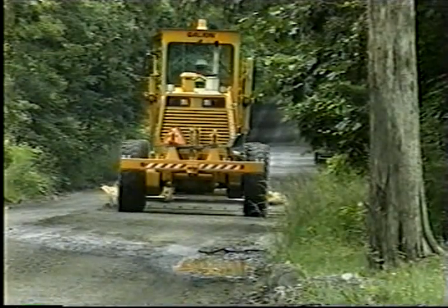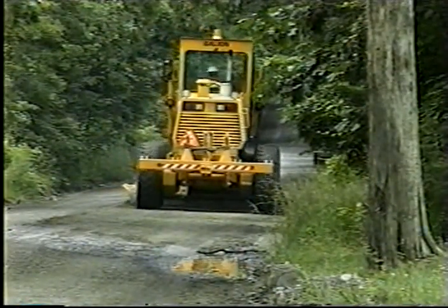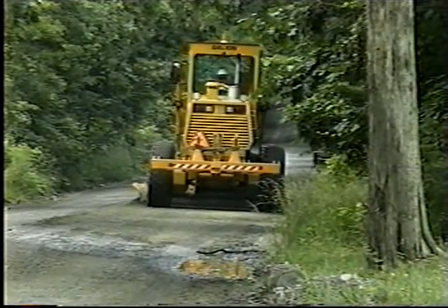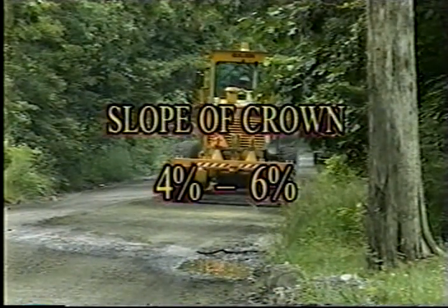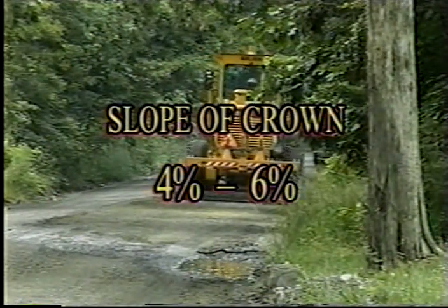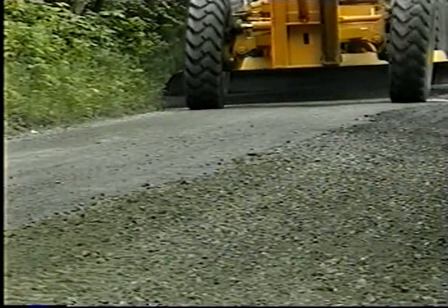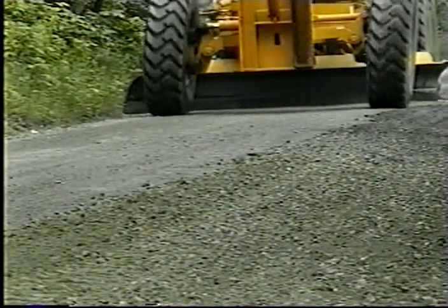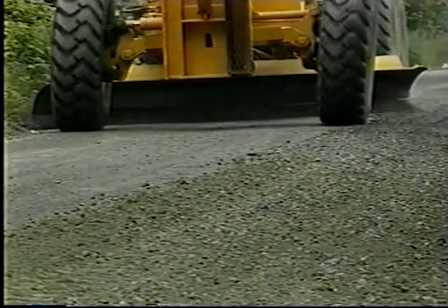Preventive maintenance also includes maintaining the cross slope. Aggregate surfaced roads are graded higher in the middle than at the sides to form a crown that lets water flow into the ditch. Good drainage requires a crown of 4 to 6% measured from the center of the roadway to the outside edge. Roads with poor crowns trap water, causing the crust to become saturated and break up, eventually producing potholes, washboards, and a poor riding surface. A groove at the outer edge of the road surface should be avoided, or a secondary ditch will be formed, preventing proper drainage. Full-width grading should be done instead.